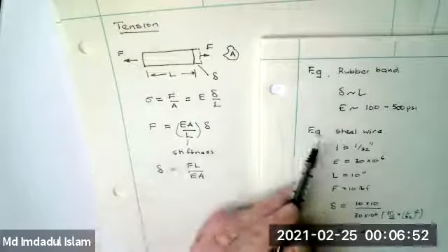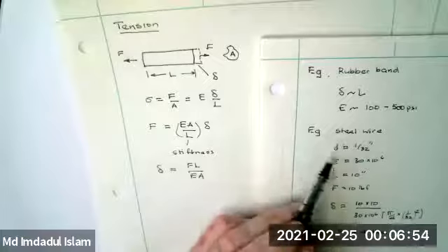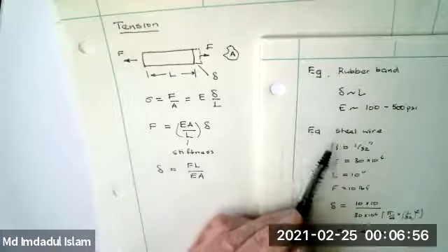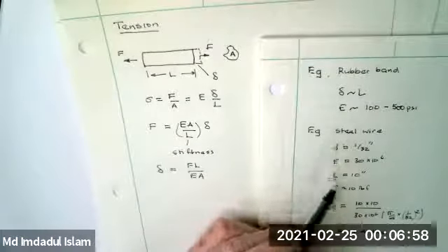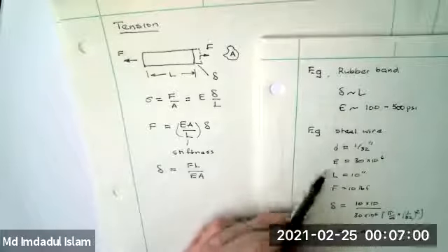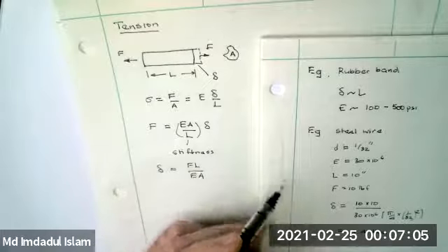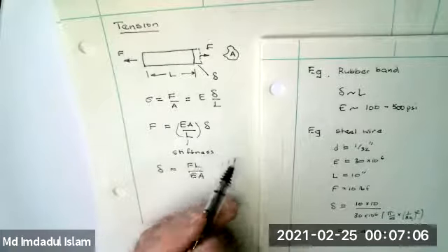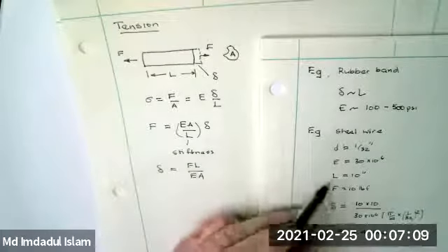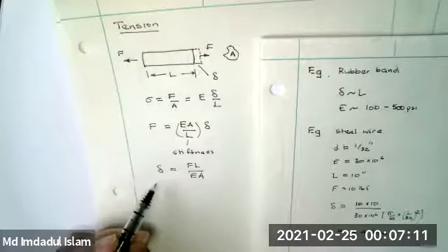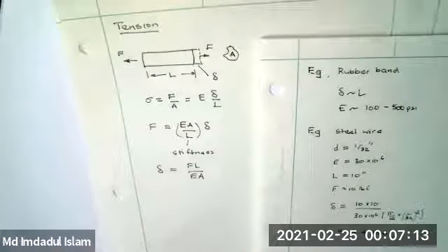On the other hand, when you start to put together composite columns, as will be in problem set 4, or other structures, then you need to take account of the deformation in order to get the distribution of stress, because they're statically indeterminate. So while the numbers are small in practice, the effects can be significant. In fact, if you don't take account of them, you will not be able to solve the problem.